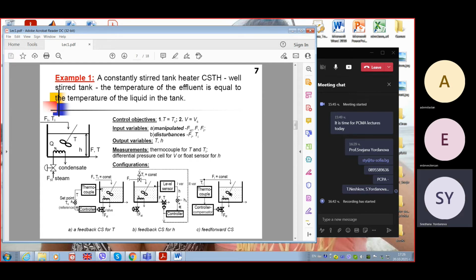So we have an open loop controller. The controller is called a compensator, and its aim is to influence this opening and supply the heating agent before the new temperature of the inflow has impact on the same temperature.